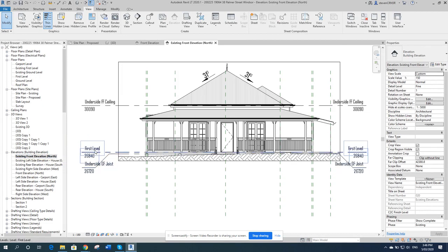But we normally do it to keep our levels as well. So if we're raising this house, then that's a whole another process of doing it, because Revit runs off of levels. The way we need to do it, that we find the easiest, and people do it differently, is to draw the house, don't show the number on here for the level height, draw it at the height that we're going to be at, so we work that out, and then we will copy the topography up.